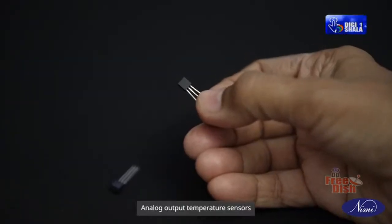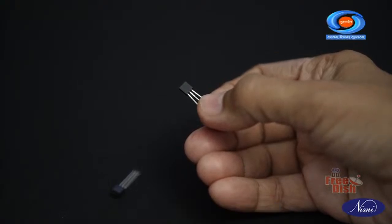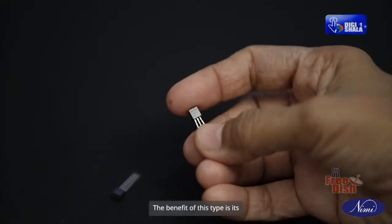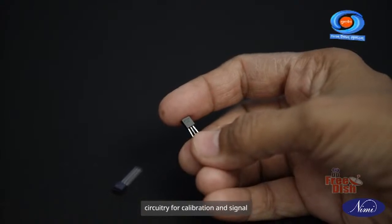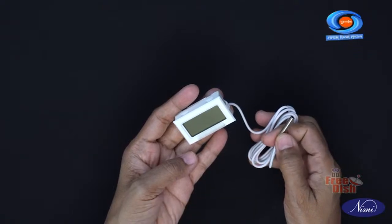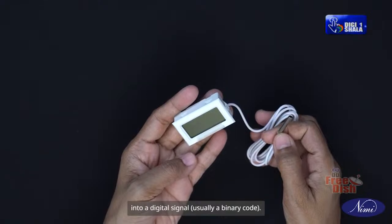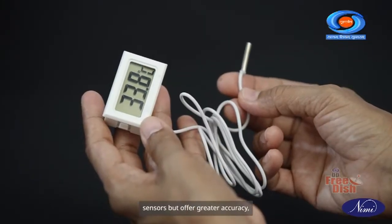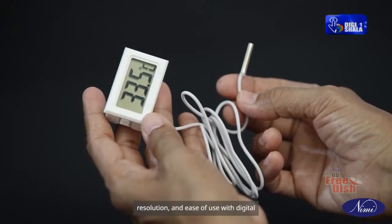Analog output temperature sensors. These sensors produce an output voltage or current that is directly proportional to the temperature. The benefit of this type is its simplicity but may require additional circuitry for calibration and signal processing. Digital output temperature sensors. These sensors convert the measured temperature into a digital signal, usually a binary code. They are more complex than analog sensors but offer greater accuracy, resolution, and ease of use with digital systems.